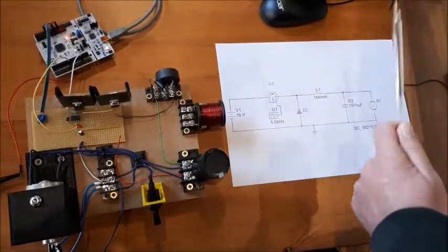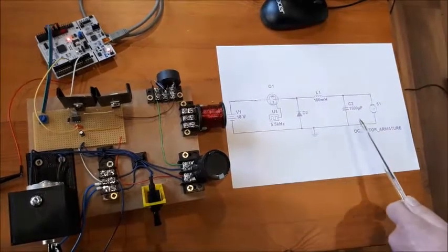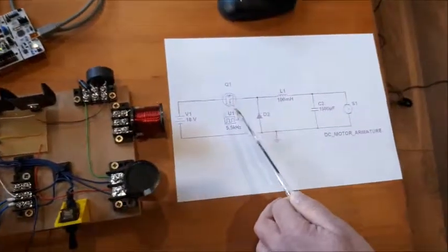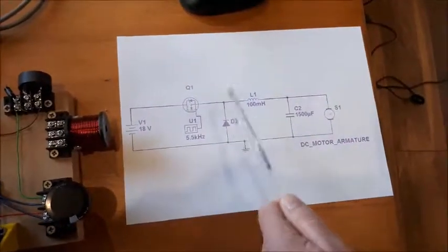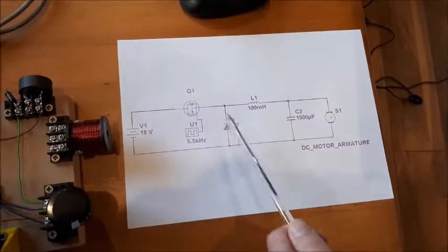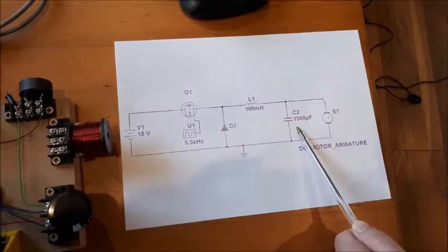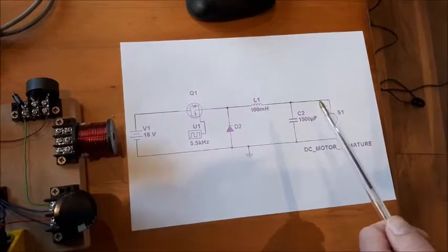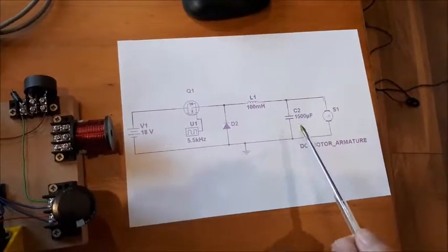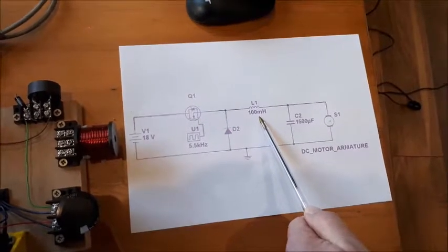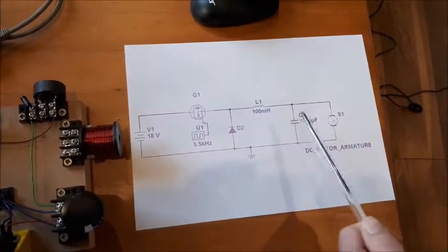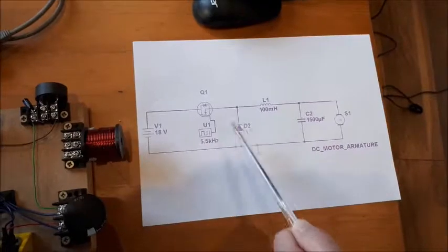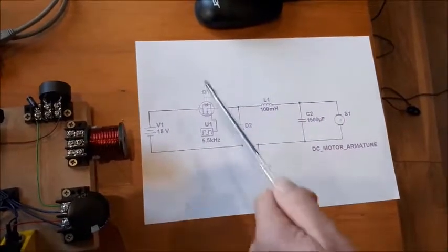Right, the capacitor is added to the circuit to provide smoothing of the output on the drain of the MOSFET, which is a replication of the driver circuit, T1 of the pulse width modulation, which causes ripple on the voltage output. The issue with the capacitor is that on switch off it causes a huge current spike which can burn out the MOSFET. Therefore, the inductor is added to counter this, but the issue with the inductor is it adds a huge spike with turn on. Therefore, to counter this, the Schottky diode is added to dissipate any current around the circuit and away from the MOSFET switching.